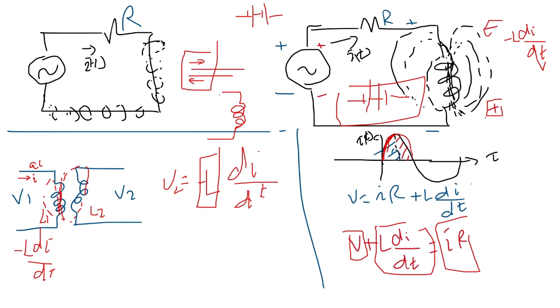Self-induction is the phenomenon by which a changing magnetic field is generated around a coil due to an AC current passing through the coil. This changing magnetic field would in turn generate a back EMF on the terminals of the coil. So the first coil, having a current passing through it, would have a magnetic field and a back EMF due to self-inductance.